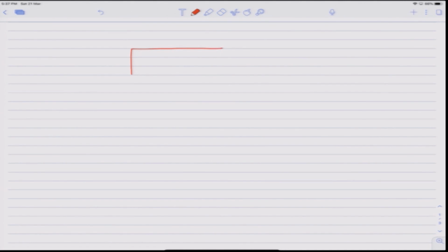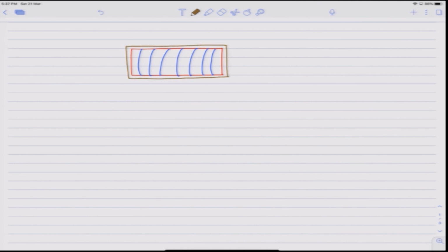So, what they did, they took a rectangular bar of brass and they wrapped that bar with molybdenum wires, then they deposited about 0.1 inch thick layer of copper onto this block.